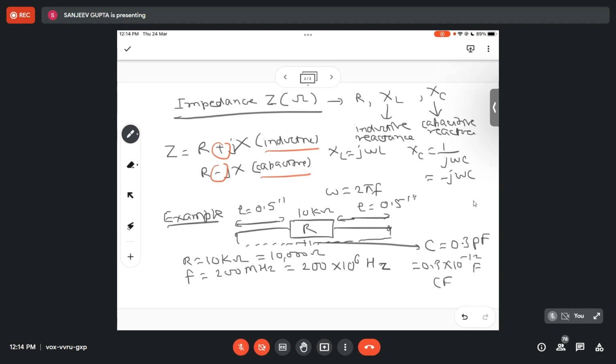So this becomes my capacitor in farad. This is normally provided by the manufacturer, because when you fold the leads, they will come out only a particular distance. So C is equal to epsilon A by d. Am I right?